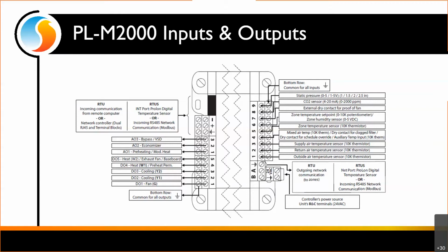And the last one is called auxiliary temperature input. That's simply for monitoring purposes, in case you just want to monitor a fourth temperature which isn't necessarily related to the actual rooftop operation. I've seen it used for some space which might not have its own sensor, or maybe in a restaurant where they wanted the temperature of the freezer to be monitored and so on. So here's just a general input which can be used for any kind of temperature sensor which you would want to monitor.